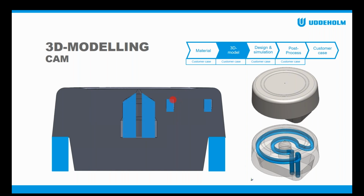And in this case, this would be devastating, because this would be really hard to remove afterwards. Imagine this is also steel that is printed. For these outer sections, you could either remove it manually or mill it away. But in these inner sections, it would be really hard to remove. And then the cooling wouldn't work, of course. So what we would do is ask you to redesign the part, maybe add some material here, and make the top more round, and then it would be possible to print it.